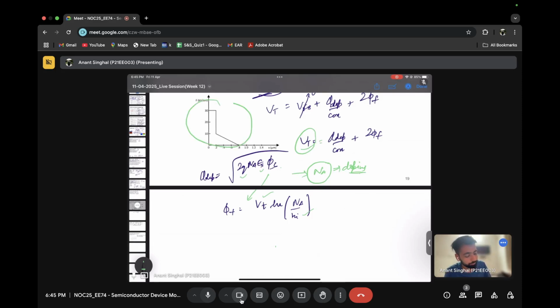By seeing this. You see that there is this electric field change, right? If you remember, in the p-n junction diode also, the electric field looks something like this. Wherever there is this peak, this is called Emax, right? And the formula for Emax was nothing but q Na times the width of that particular region by epsilon s.